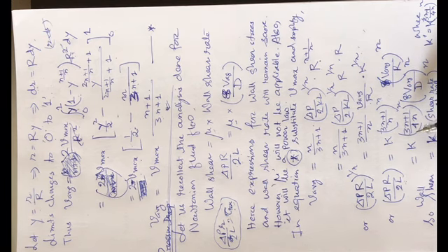You just see k, 3n plus 1 by 4n. Now this R is basically half D, so we are multiplying by 2 here. Therefore we are multiplying 2 in the numerator as well: 2R, twice V average. Again here we are multiplying in the denominator another 4, of course with the power n. So similarly here also we will be multiplying with 4 to the power n. So 2 coming from here and 4 coming from here, it becomes 8 to the power n. So 8 V average by D, to the power n.